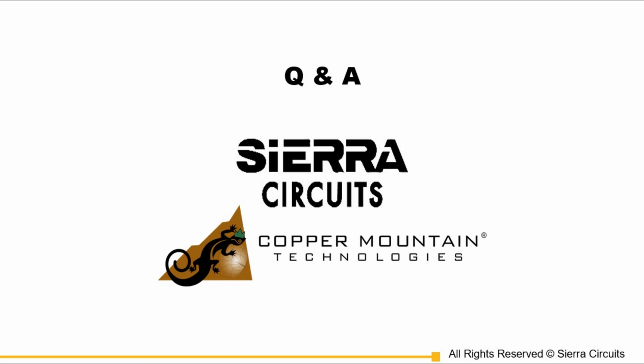What is the next? How does conformal coating impact insertion loss? Any kind of coating will increase the loss. Every coating, conformal coating, whatever the material, will have a loss tangent. Therefore, it is going to increase the loss.